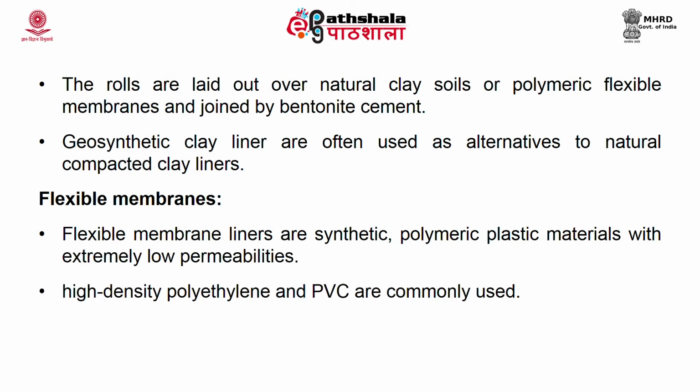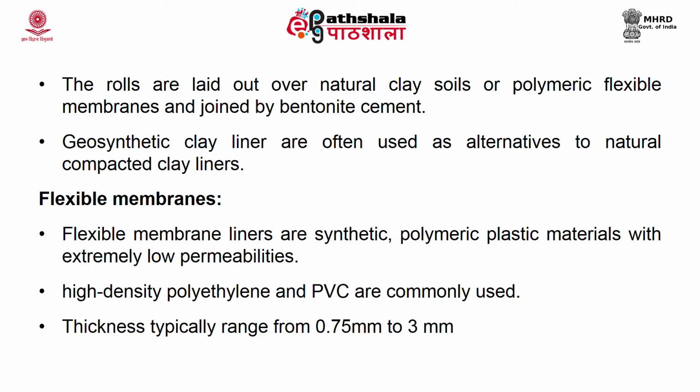The next type of landfill liner material is the flexible membrane. Flexible membrane liners are synthetic polyplastic material with extremely low permeability. High density polyethylene and PVCs are the common types of materials used as flexible membrane.